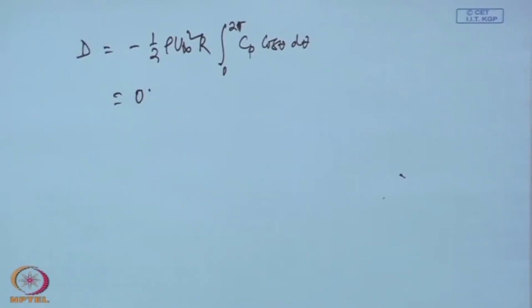And not only that, since a circle or cylinder has such a symmetry that even if your flow direction changes, the body is still symmetric. There are certain cases where if your flow direction changes, then the symmetry may be lost. So, consider the case of the Rankine oval. In that case, if the flow was in the x direction only, it was symmetric, but if the flow direction made some angle with respect to the x axis, then it is no longer symmetric.